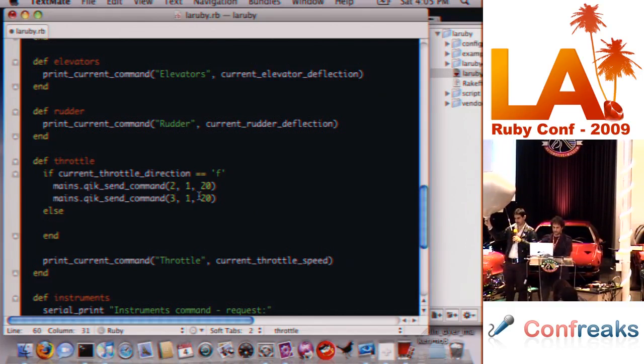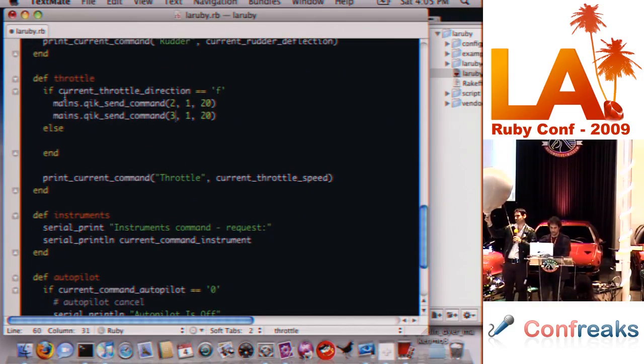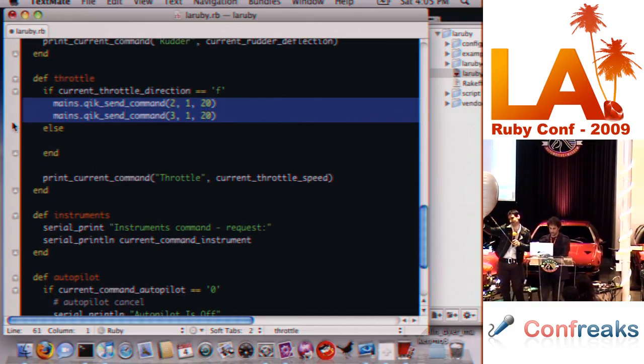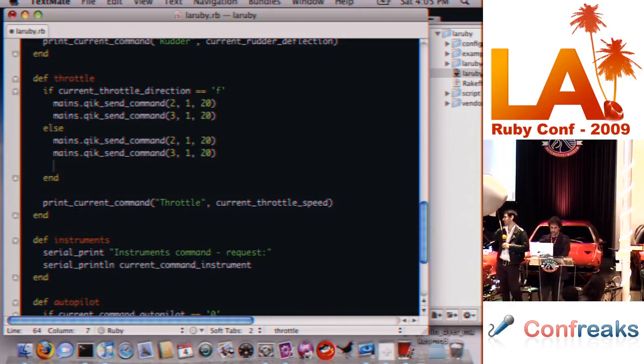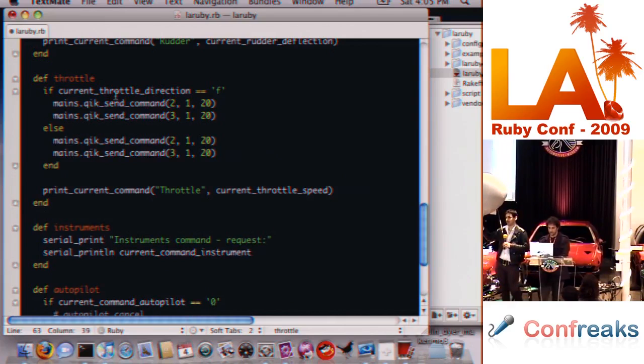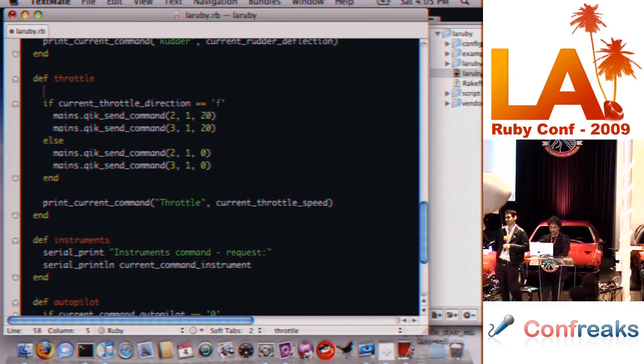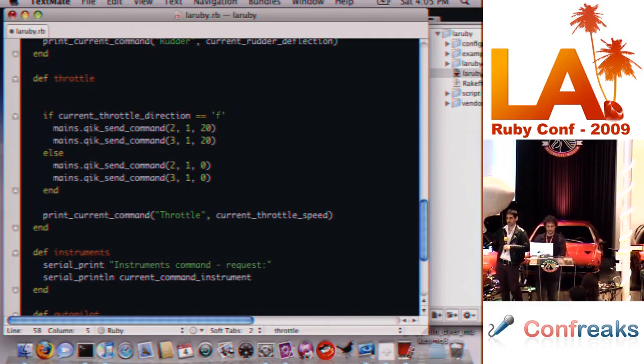Anyway, with the upgraded motor controller, we're able to get a lot more power through the motors. In fact, so much power that if I go full throttle, the spin of the motors itself will cause the thing to careen off in the other direction, sort of like a helicopter rotating. This is something we didn't really expect to happen in something this size. We didn't think we'd ever get it going fast enough for that to be an issue. So a fix we have planned is reverse pitch propellers, so we counter-rotate them so that they just go straight forward, hopefully.